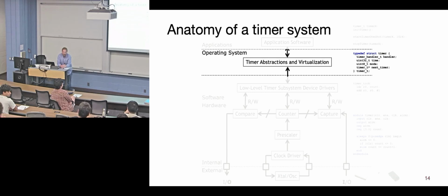Press go and never stop. Well, but you only have 16-bit timers, and your clock only goes so fast. I would use a counter that when it finishes, I use another counter. So in software, you have the clock as a counter. When this counter runs out, it enables another counter. It adds a 1 to another counter. Okay. And when that counter finishes, it adds a 1 to another counter.